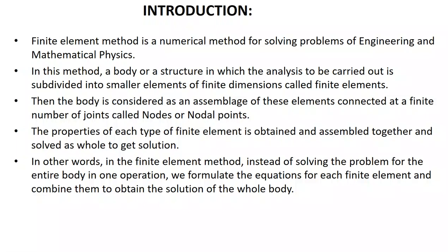Initially it was a structural model, now it is a finite element model. The point where the small elements connect together is called a node or node point. These nodes are where we give any inputs to the structure or take outputs from the structure. That is why we need nodes.